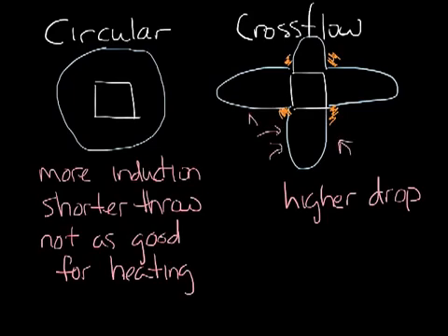As the supply air comes out of the cross-flow diffuser, room air is induced into the edges. Since there's no airflow out of the corners, dirt in the induced air can collect in the corners. Circular airflow pattern diffusers don't usually have smudging because the air flows from all around the diffuser, so there's nowhere for the dirt to make contact with the ceiling.